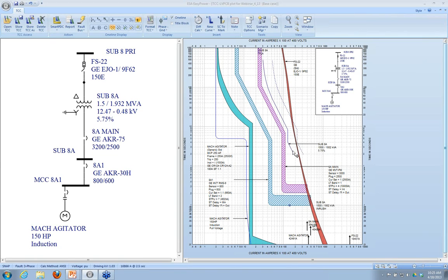This is the long time pickup. By adjusting these two delays so that they don't touch, these two breakers, the main and the feeder, will coordinate completely for all ranges of fault current. So I don't have to worry about these two coordinating. They should fully coordinate, assuming they both work, for any fault that's going to occur on my system. And I can do this because these devices have a withstand rating. They have that 30 cycle, so that allows me to not have instantaneous.